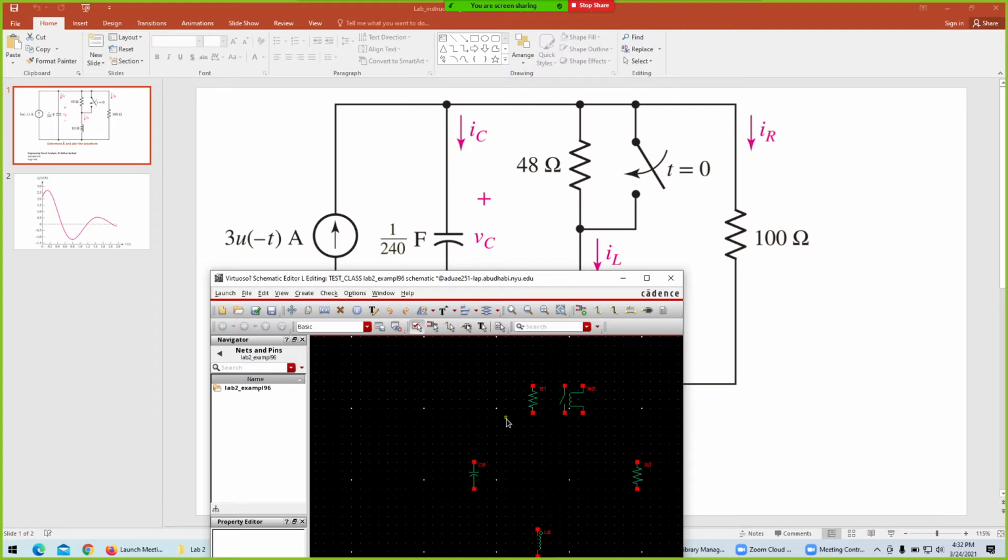We know when we have a switch, we need a source. Actually, not a plain voltage source, we need a piecewise linear source to activate this switch in a timely fashion. Looking at the circuit diagram, the switch was open until time 1 second, but right at the next moment, 1.00001 seconds, the circuit is closed.